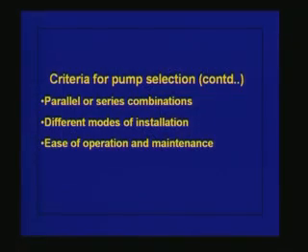That is, the first pump will lift the water by, let us say, a certain amount, then the second pump takes over and for the same amount of discharge it lifts the water by another amount, and so on and so forth. So whenever we are selecting the pumps and doing the design of a pumping installation, the number of pumps is important. Whether these pumps are operating in parallel or in series is another important consideration that we need to decide right away before we go and select the pump.